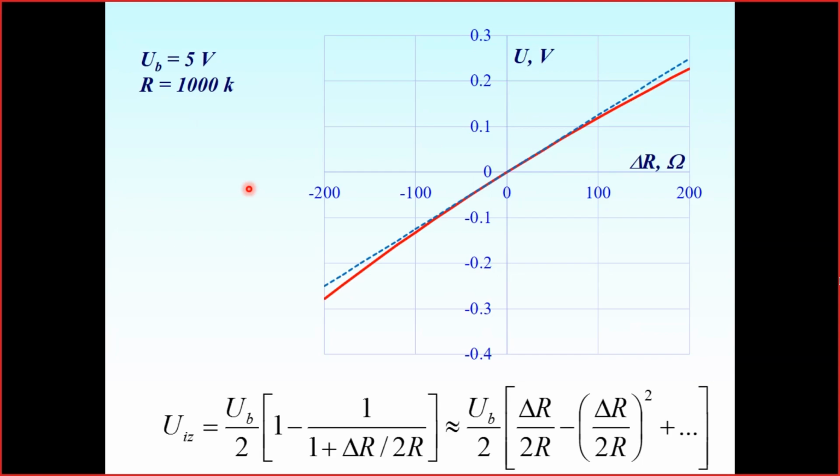And what is important, if we use, for instance, just a voltage divider, we may do this as well, but the advantage of the bridge is that its output is 0 and we have no effect from the transducer. When we apply some pressure, some outer signal, to the transducer, then we have some change in output.